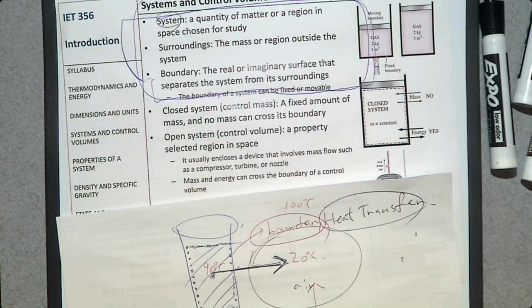Boundary is going to be the device. And the surrounding is going to be whatever the fluid inside the air conditioning system, that's going to be refrigerant. So you can study the energy transfer between refrigerant and air circulating in that air handler. So that can be one thermodynamics problem. In that case, air is coming out and then goes in. So you can consider the air conditioning system as an open system.